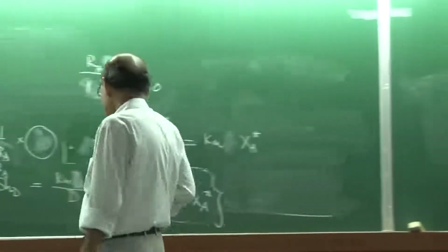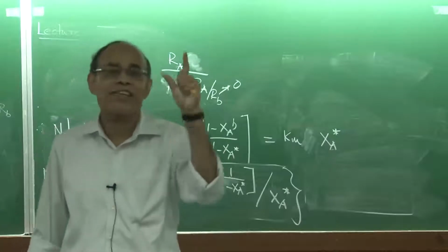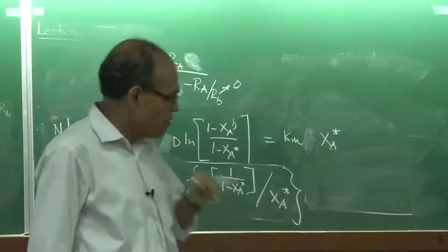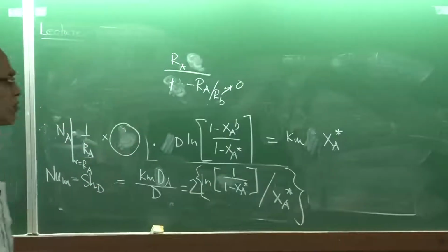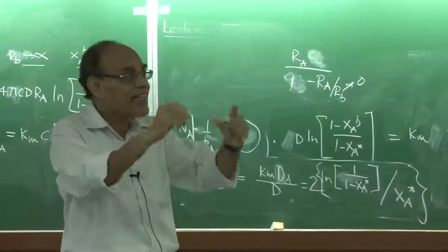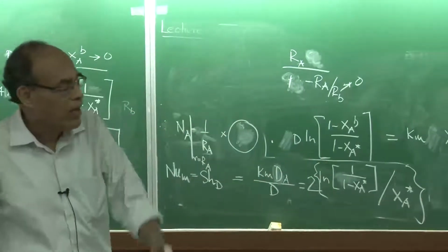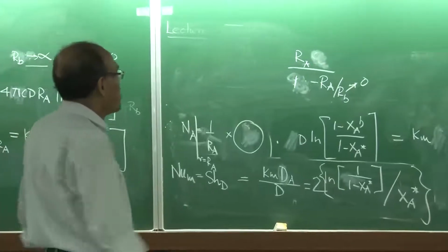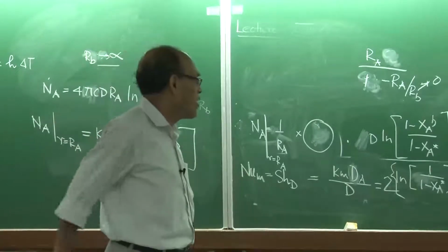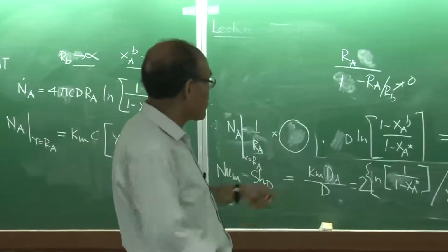So, we now know that dealing with a pure diffusion situation is exactly analogous to the heat transfer situation. Whatever we have studied in heat transfer can be straightforwardly applied to mass transfer. The moment you look at it, my governing equation is exactly identical to the heat transfer governing equations; there is a one-to-one correlation between heat and mass transfer phenomena. Only by manipulating the different property values should you be able to extract the solution.